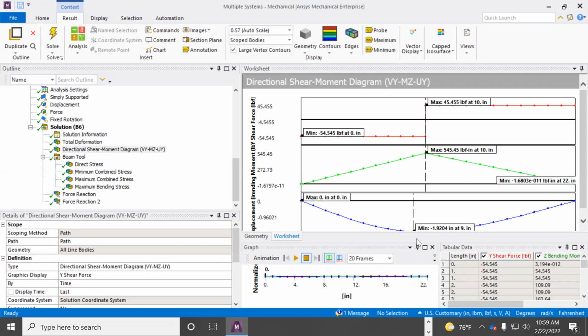And the one last thing I want to leave you with is when you're working on shaft problems, we have bearings. What do the bearings do? They allow it to rotate on axis. Correct. They allow it to rotate, they allow it to spin, but they do not allow it to translate. So when you're trying to model a shaft, for the bearings I can use simple supports and apply them to the vertex. So we're going to use center line to center line direction.